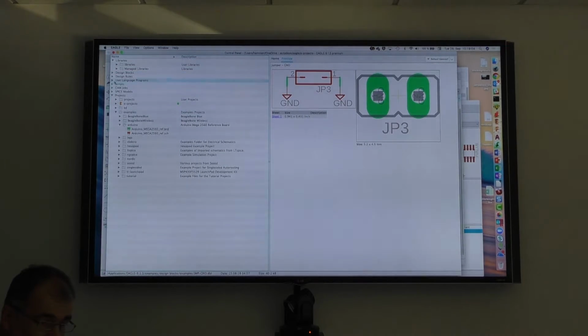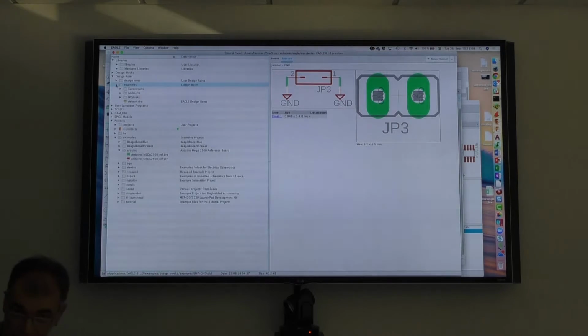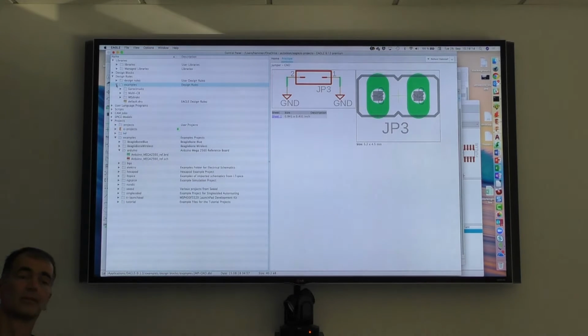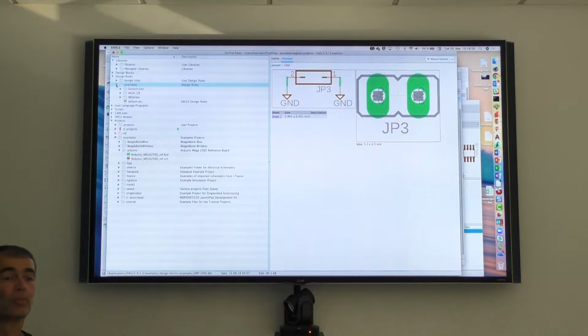Design rules. Talking about design rules. Okay, these are rules for the layout, for the manufacturing process. You know, the board manufacturer tells you, okay, we can handle copper structures of 150 micrometers. That's the default, the standard we have, at a reasonable price. If you want to have smaller ones, then it's getting more and more expensive. Then you have to adjust your design rules.